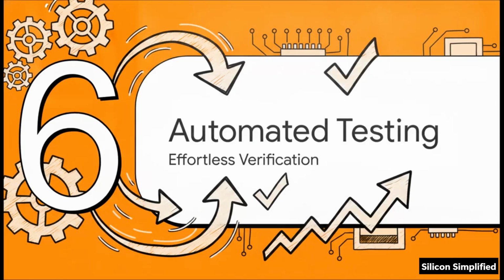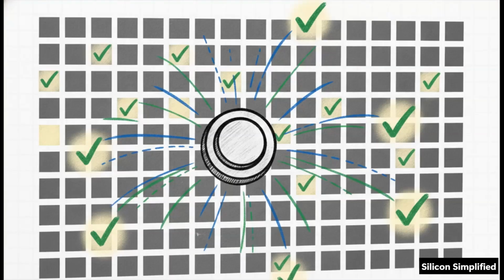Section 6. Automated register testing. Effortless verification. Now, the real magic happens with just one single method called do_test_all. Executing that one line triggers built-in UVM register tests that verify reset values, access policies, and reserved bits across your entire design. I mean, think about that. You don't have to write a custom test to check if a read-only register accidentally accepts a write. You don't need a sequence to ensure every register correctly resets. UVM provides these predefined sequences that sweep through your entire auto-generated model and thoroughly stress test the hardware completely automatically.